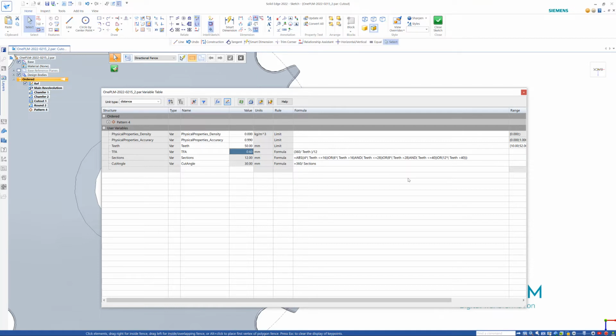So if you've got hole centers that need to change depending on the size, and when it hits a certain size, bang, the hole changes from 300 to 450, for instance, we can use this same option. If you do end up with gaps between before and after teeth, notice the one I'm going to do, there aren't any gaps, but it will automatically add a gap in here. So if you write it in Notepad or Word or something, there's no need to put the gaps in. When you paste it, it will automatically add those gaps because it recognizes that it's a variable.